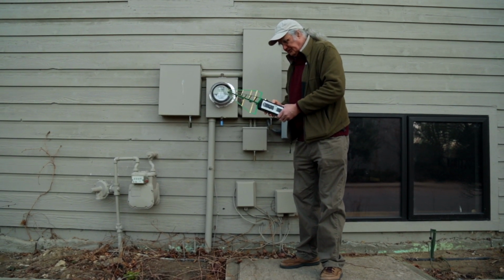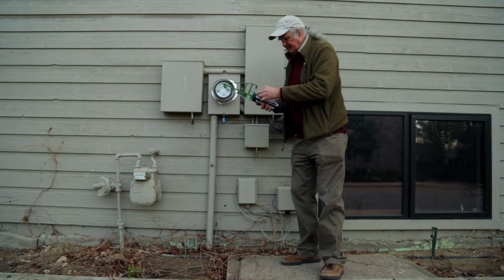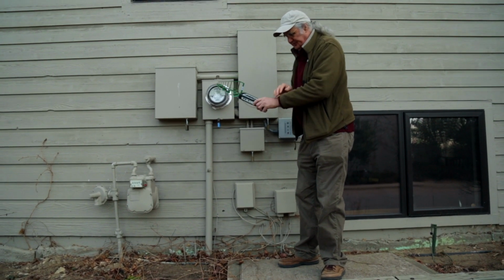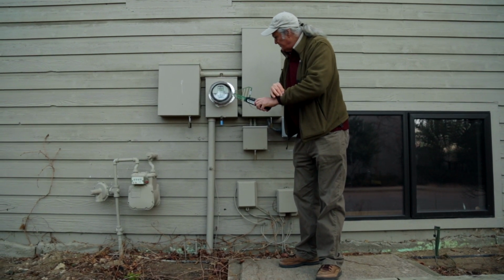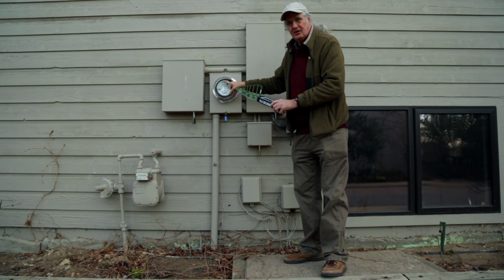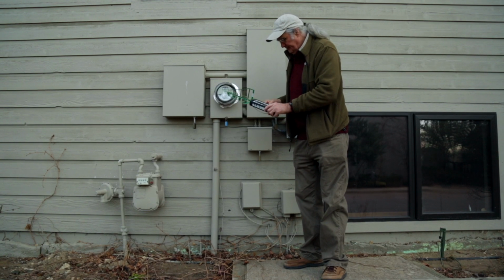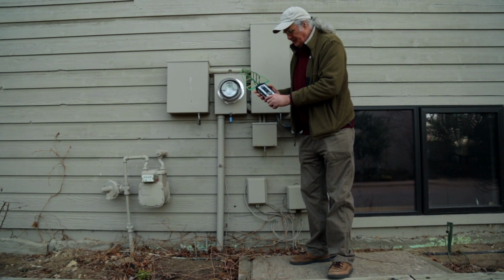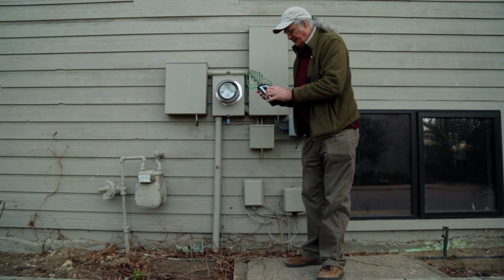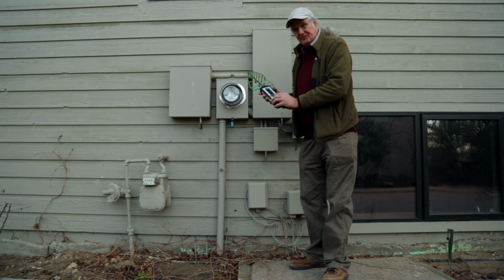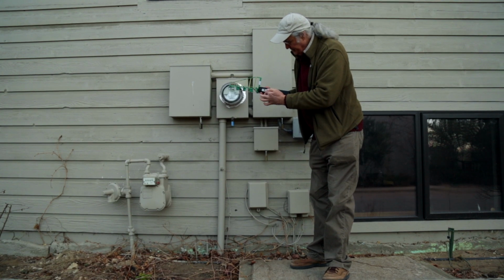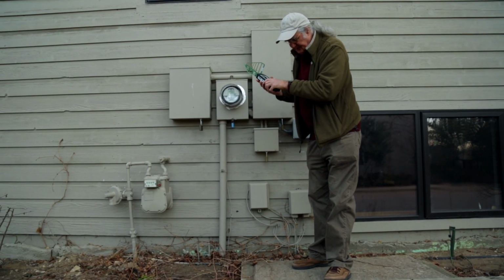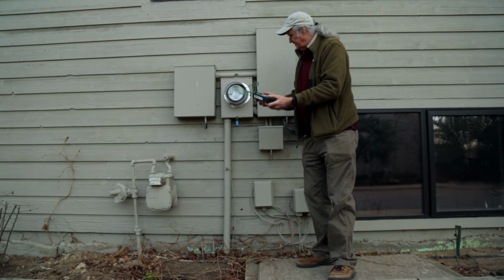Now I'm going to turn on this meter here. Actually, I've had it on, but I'm going to turn the volume up. And it turns out that this particular meter, made by GE, but this is an Itron, I-T-R-O-N, transmitter inside, air. And so we heard, saw a 5,000 microwatt per meter squared level. Now I'm going to put this on peak hold and watch here. So in about 20 seconds, this will transmit again.